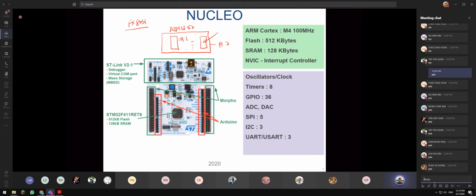It's a development board with built-in LEDs and ports. Students can insert the input-output ports, and we link to the PC through the UART, meaning RS232, the old type of communications platform, 9-pin. Those days you used a serial port connector. So what I did at that time, I designed the whole board. Microcontroller 1 and microcontroller 2 are linked through SPI. We're going to learn SPI later.